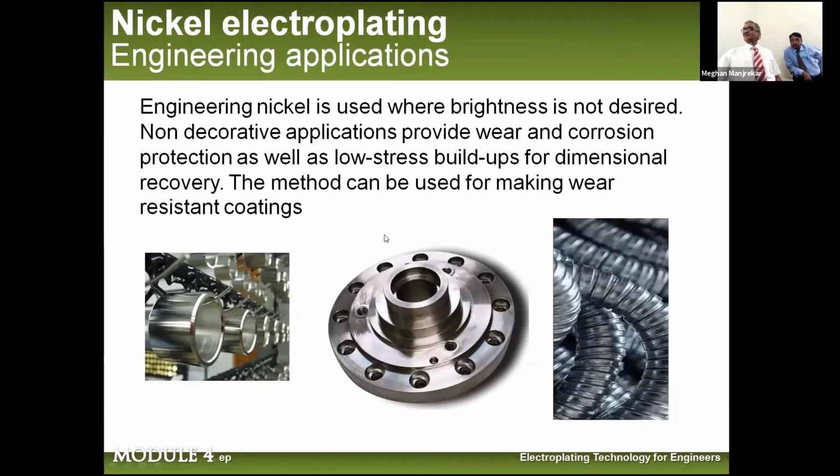Engineering nickel is used where the brightness is not desired. Non-decorative applications provide wear and corrosion protection as well as low stress buildup and dimensional recovery. The method can be used for making wear resistant coating also, which we normally call hard nickel or engineering nickel.